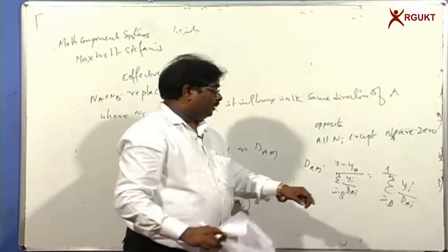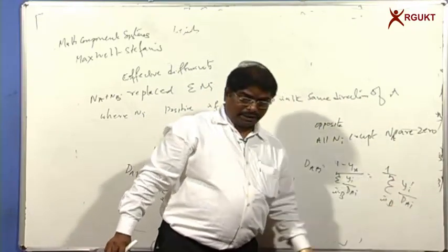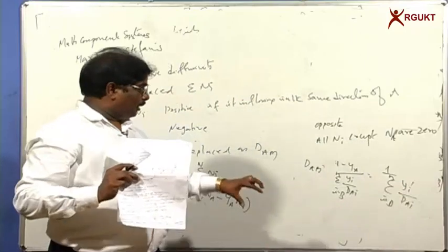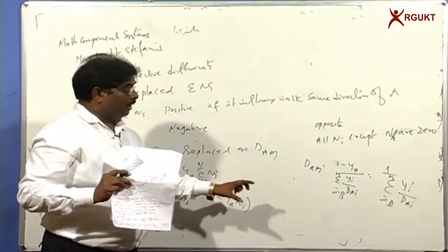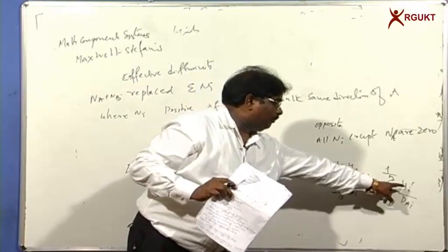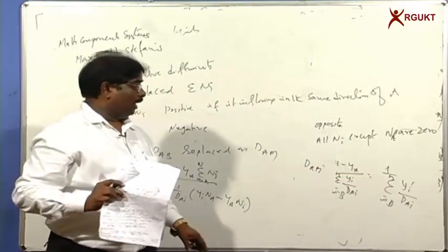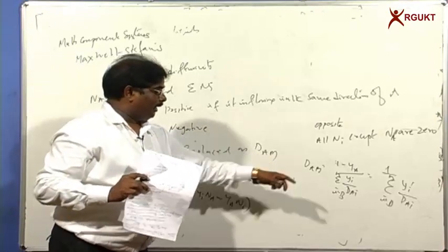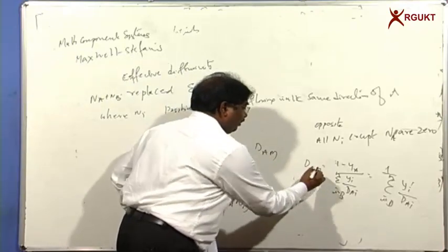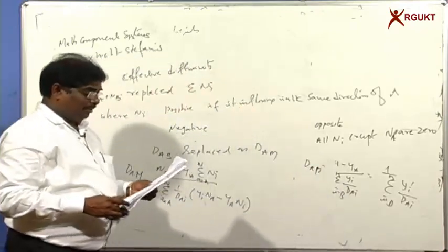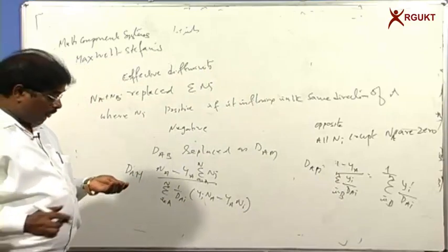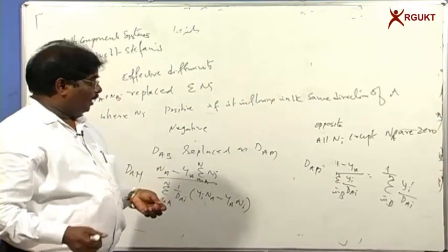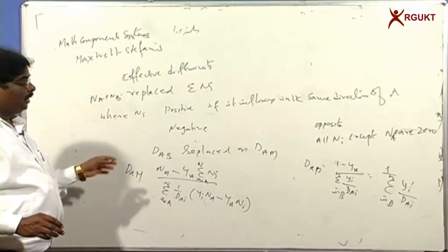Here yi′ contains the mole fractions calculated on an A-free basis. So on an A-free basis one can calculate DAM, and once you know DAM, you can use the previous equations to calculate the fluxes. So this is what I wanted to talk about with you in this class.